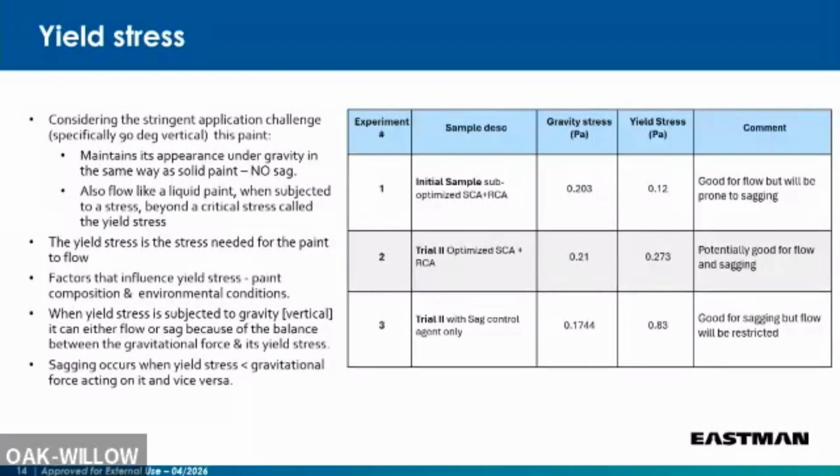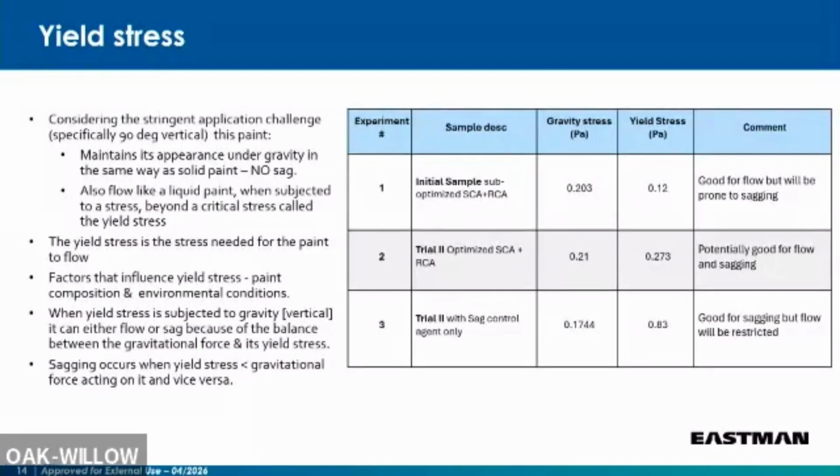Okay, next question. How did you select the dry film target film build range? No, we went by the OEM specs, because like I told you, when you started the project and they explained to us that they want a single coat, you should not wrap, because you realize this is almost like a shower head. You are just pouring paint, not atomizing it, and you want the paint to stick over there. So we thought, okay, maybe they may be just looking for 5 microns or 10 microns. Because I told you, if it is zinc, you can do that very easily.